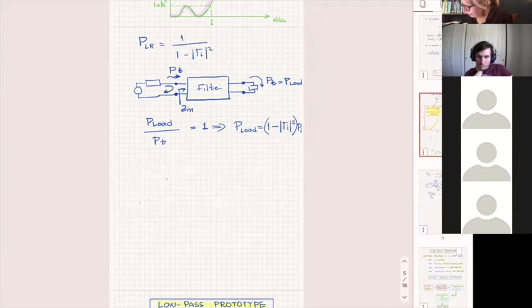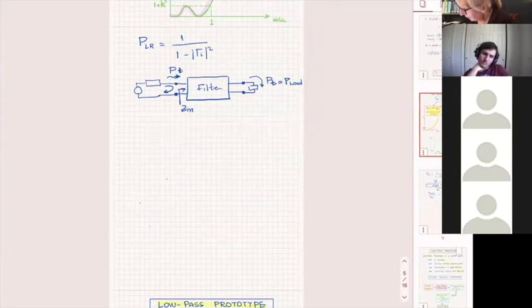I have been able to match my load and get the best filter design. This is my initial load. My real load is here, and the filter is in between. So that my Z input here is the complex conjugate of ZS, or Z input complex conjugate is ZS. Does not matter how I write it. In that case, I did conjugate matching.